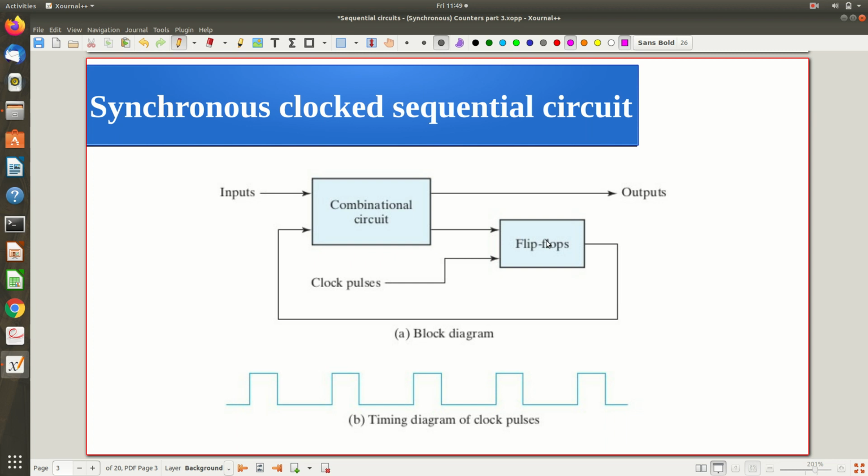In all the subsequent designs we will see only flip flops, because they are clocked latches, so they work in synchronization with the system clock. That is what makes flip flops better than latches. Storage elements by default you can assume to be flip flops, and all those flip flops are triggered by a common clock. That is the meaning of this. However many flip flops you use, all are commonly triggered by this clock, and there will be input and output.